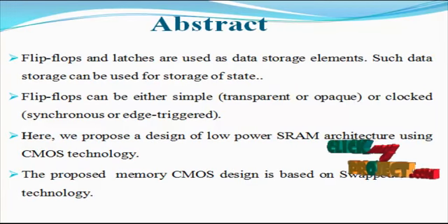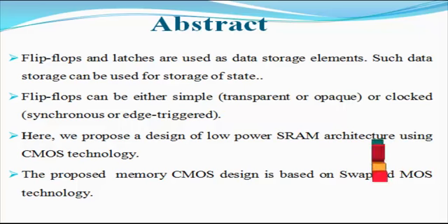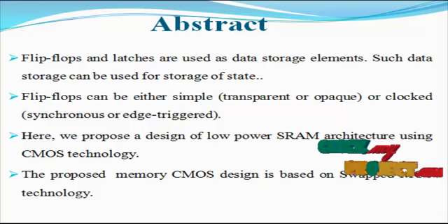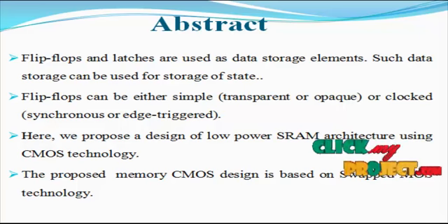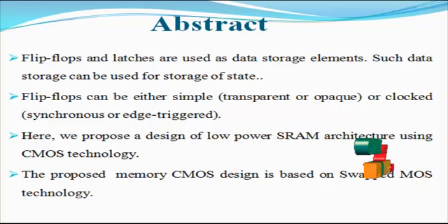SRAM is a form of semiconductor memory widely used in electronics, microprocessor and general computing applications. This form of semiconductor memory gained its name from the fact that data is held in a static form and does not need to be dynamically updated as in the case of DRAM memory. While the data in the SRAM memory does not need to be refreshed dynamically, it's still volatile, meaning that when the power is removed from the memory device, the data is not held and will disappear. The operation of the SRAM memory cell is relatively straightforward.